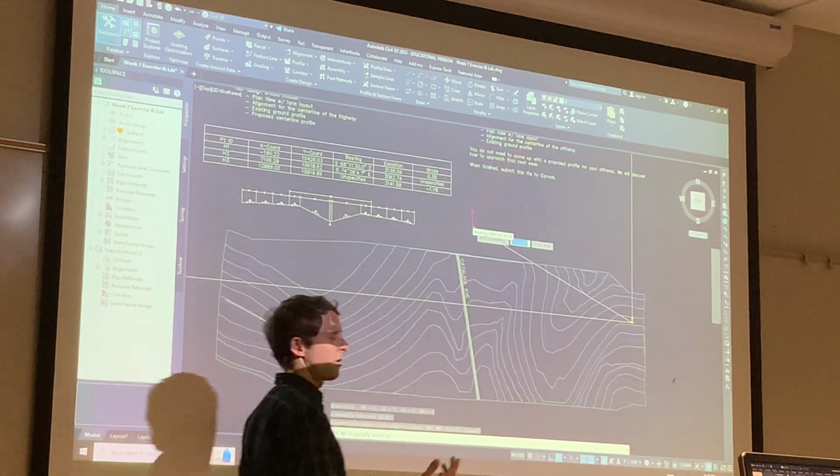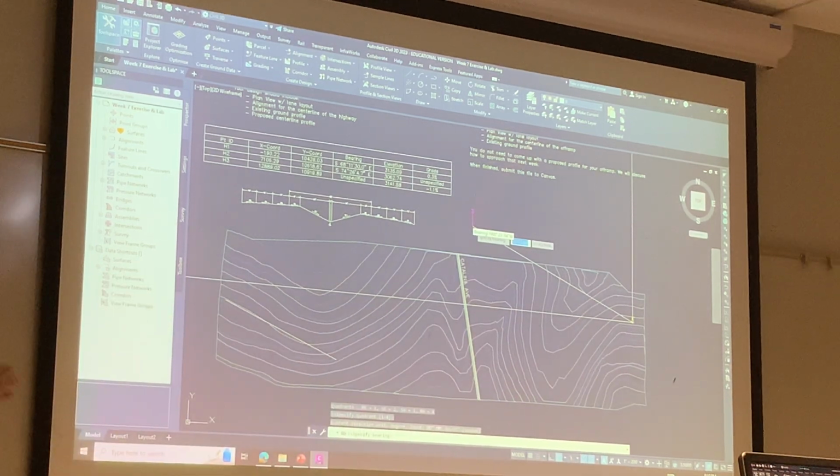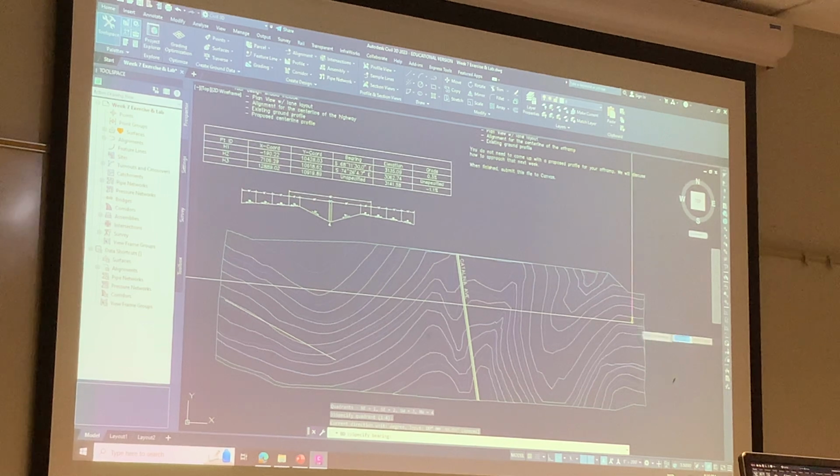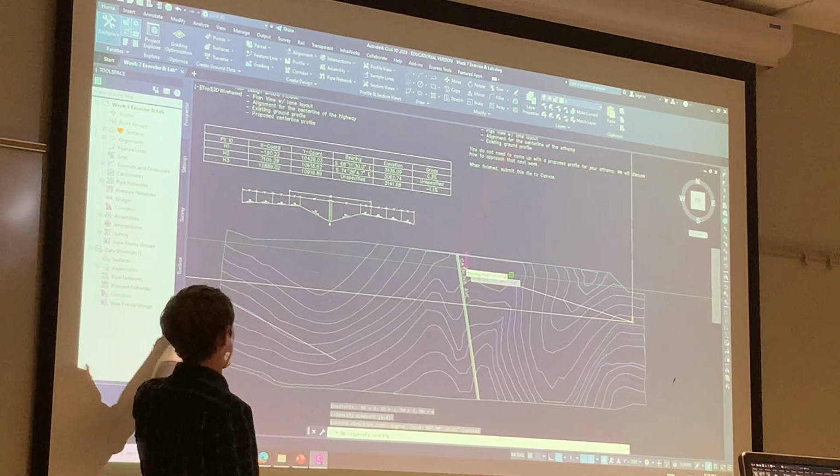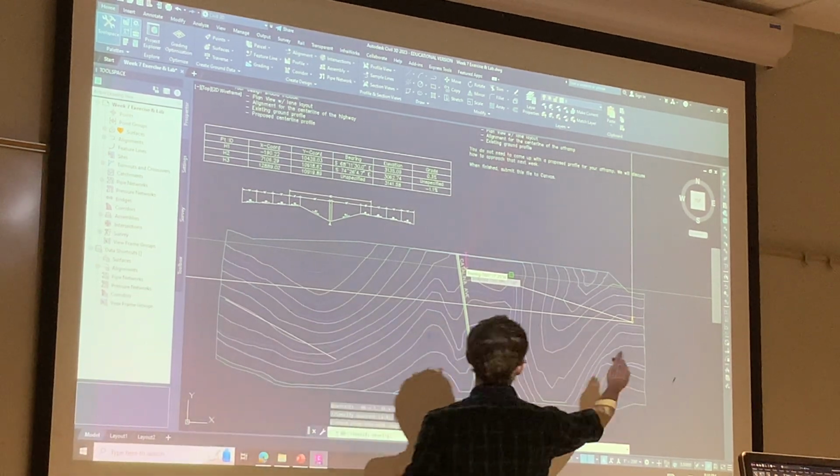You remember last week, I took that line and I moved it from end to end, I think, so that I could basically recreate this line and designate this point right here as the really important point. But if I choose quadrant 4 instead of quadrant 2, I'm drawing the same line. Now, that said, when I draw it this way, polylines have a direction. So this one I drew this way, this one I drew this way.